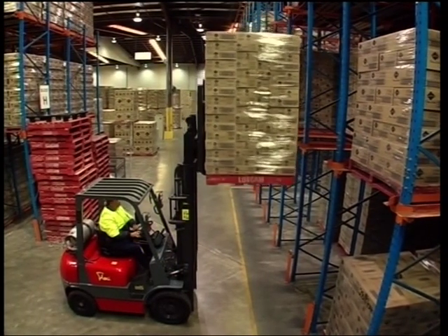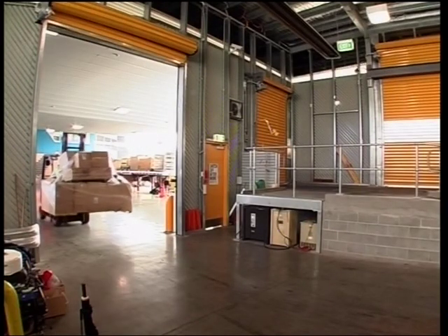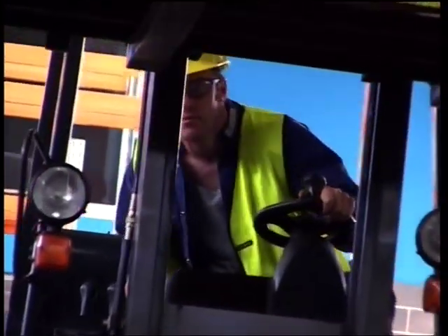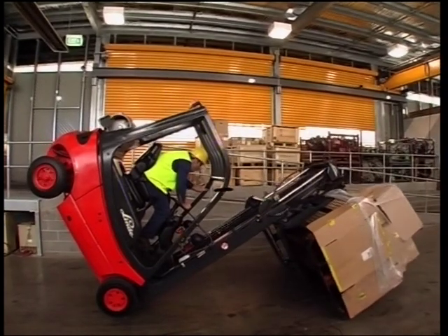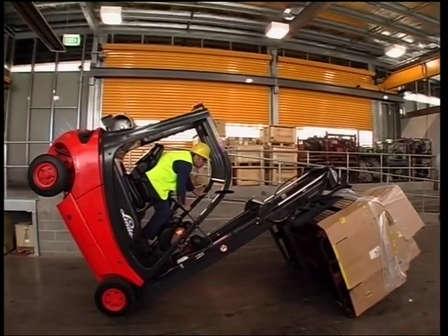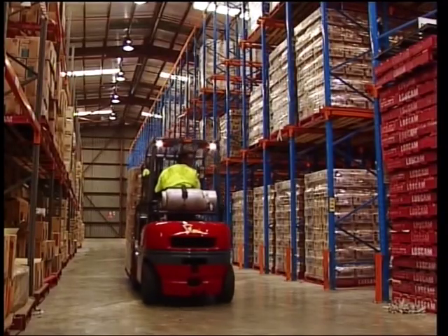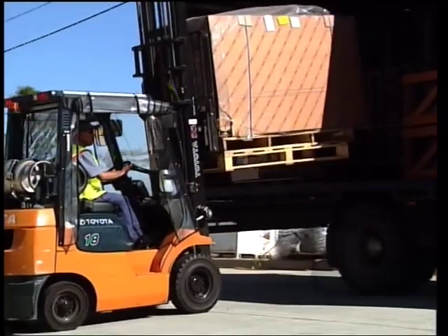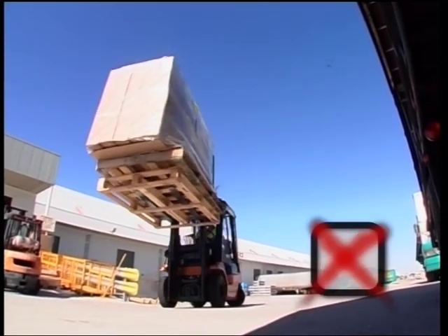Stability is greater when a load is lowered before traveling. Raising the load to see under it is an unsafe practice. The forklift could tip forward, and it limits braking due to the propensity to overturn. If you can't see over a load, drive in reverse or have somebody direct you. Never travel with a load or the forks raised, as this causes instability in all directions.